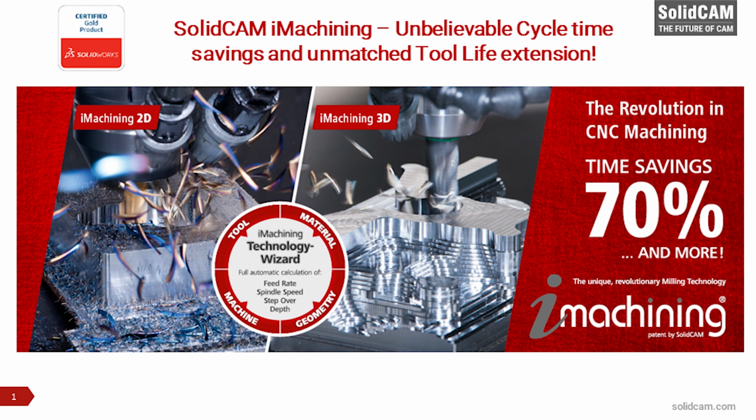One of the things about iMachining, because we're not applying a linear force to the material, and because the way we are removing the chip in such a consistent manner deflects all the heat out with the chip, we're not putting work-induced forces into those thin walls and thin floors.